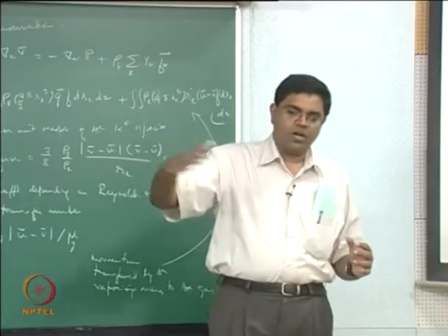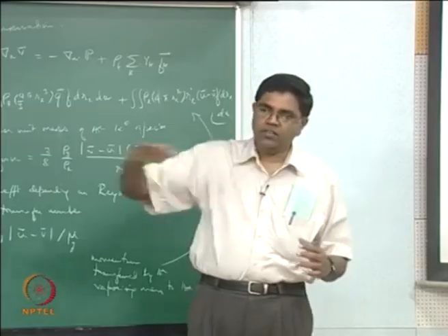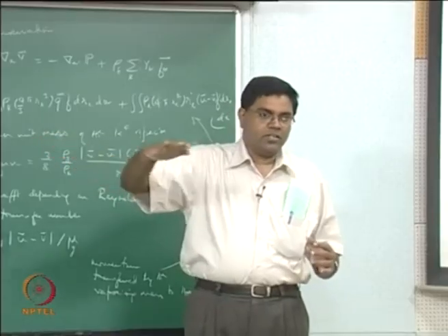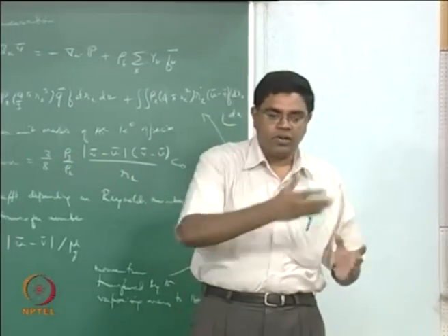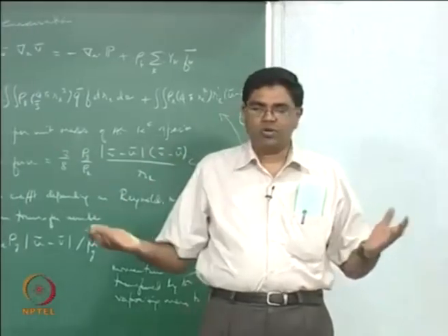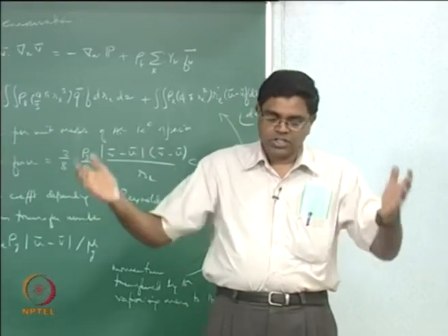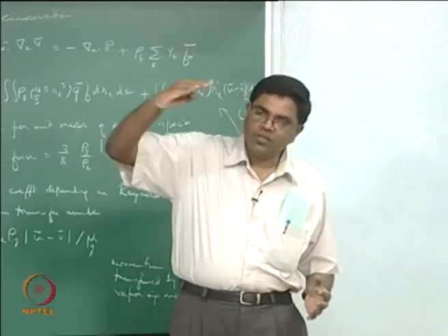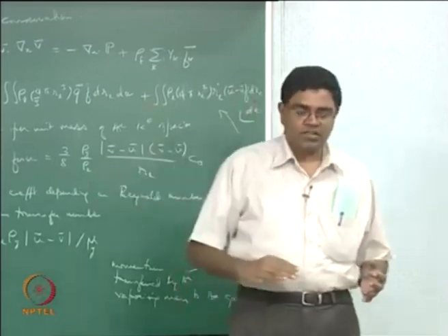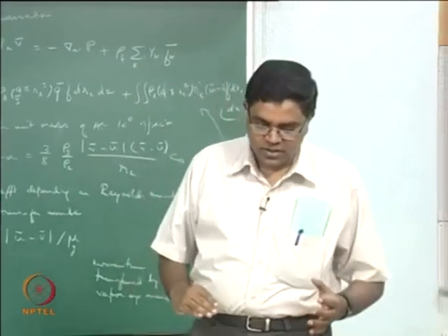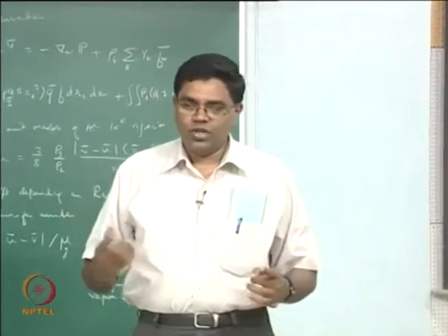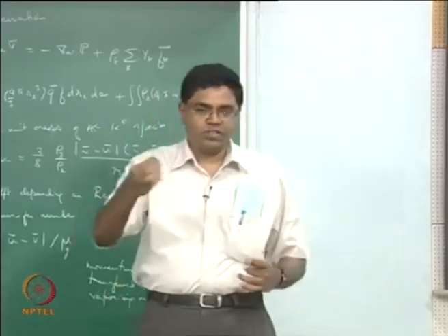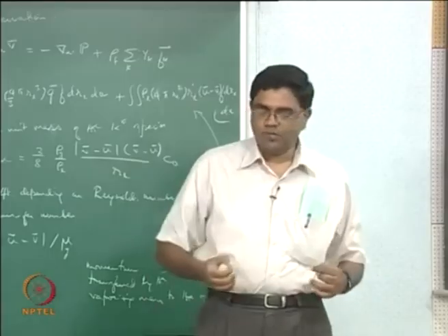So a snapshot, for example, if you were to now do something like a PIV of this and take like a planar data of what the flow field is, you will now have like a large scale motions captured over the larger area with like pockets of intense small scale turbulence here and there, because the droplets have just gone past these planes here and there. So that's typically described as a Swiss cheese, because if you now take like Swiss cheese, you now have lots of these holes. There are these holes now filled up with, in this case, the droplet turbulence.